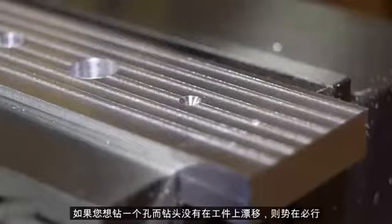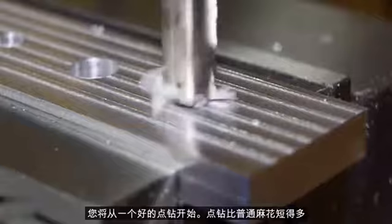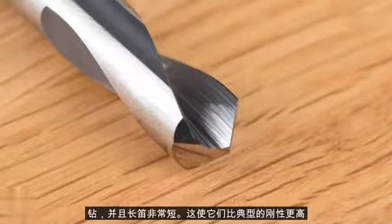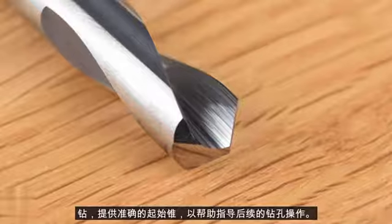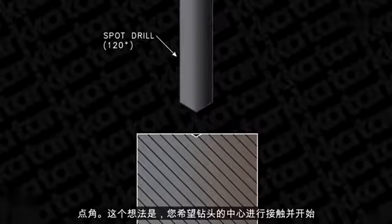If you want to drill a hole without the bit wandering on the workpiece, it is imperative that you start with a good spot drill. Spot drills are much shorter than normal twist drills and also have very short flutes. This makes them much more rigid than a typical drill, providing an accurate starting cone to help guide subsequent drilling operations.